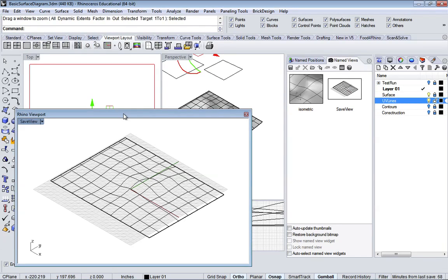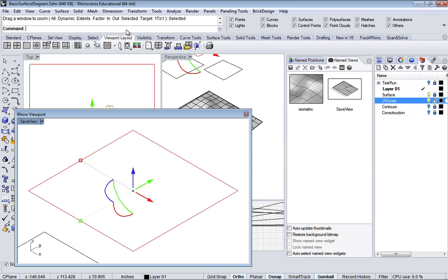Oh, I've got to make sure that my Rhino viewport is selected, the one that I wanted to see in. So let's try that again. Z, enter, and then S, selected. And bam, now we have that view set up there, and it doesn't change any of the angles or anything, but it actually has it all set up, and we've been able to move around basically that viewport.